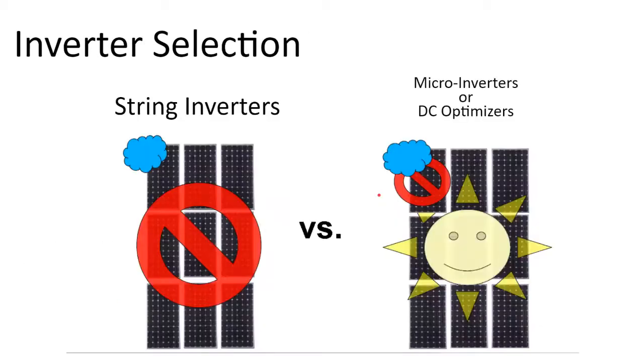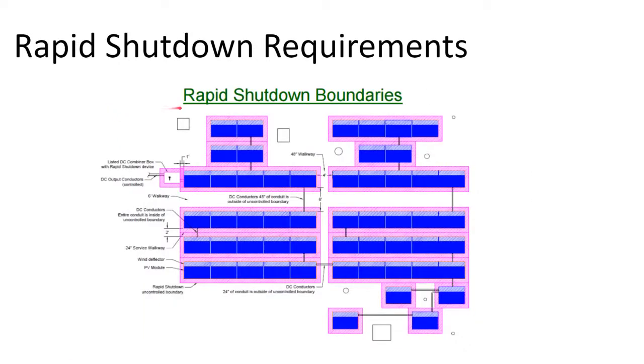In the absence of shade, which system is better is a matter of opinion. Without getting too nuanced, I'd recommend microinverters for do-it-yourselfers, DC optimizers for experienced installers, and string inverters for ground mounts. National Electric Code requires solar conductors to be de-energized on command, and a strict interpretation of the latest National Electric Code would mandate the use of DC optimizers or microinverters when solar is installed on the roof. There is no off switch to a solar panel, and so module level panel electronics are the only means to completely isolate the solar array during an emergency and bring the system voltage down to a safe voltage.